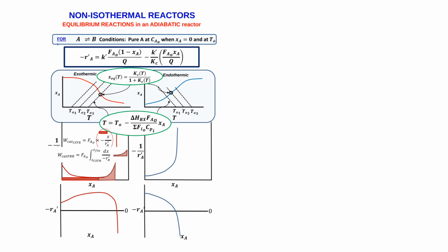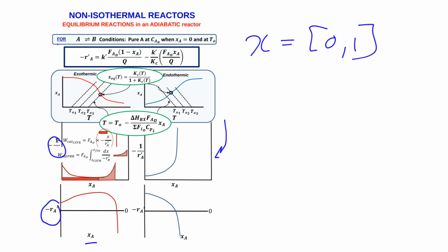So my advice when you employ this in Python, when you want to construct a Levenspiel plot to see what happens to your rate, is rather to just have a straight plot of the rate as a function of conversion. If you choose an X range of values between 0 and 1, somewhere in the middle of that range it's going to hit the point where the rate goes to 0, and then you've got a situation where you have to divide by 0 in that rate in order to construct the Levenspiel plot. That will not happen when you calculate that rate.